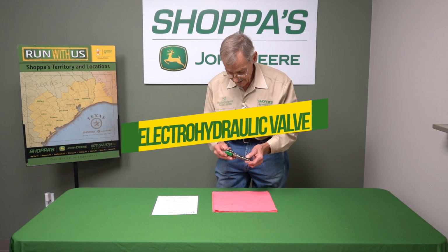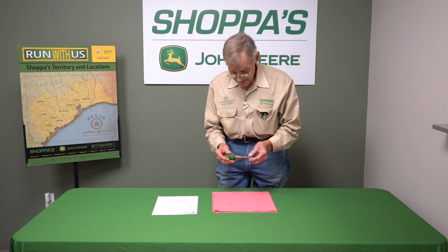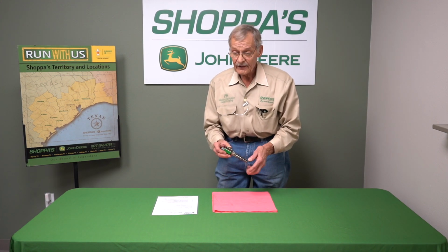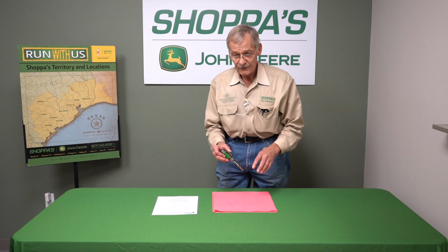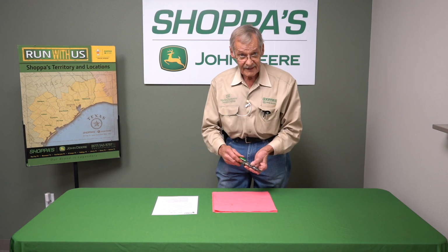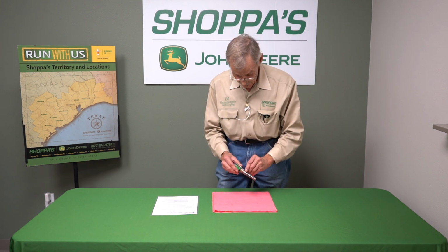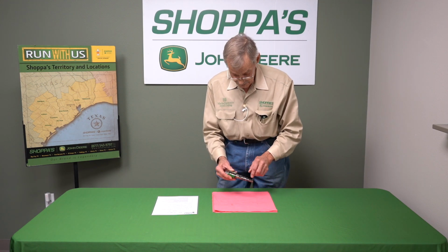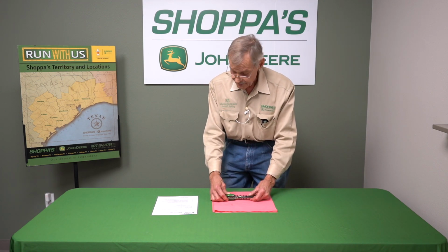Okay, our next component is an electro-hydraulic valve, which is utilized in many industries. This is to control hydraulic oil. There are some applications in some valves that control pneumatics, air, but this one is for hydraulic. You're utilizing an electrical coil to move the spool, which directs oil and also moves the secondary spool, which will send oil to different packs or components, whatever needs to be controlled.